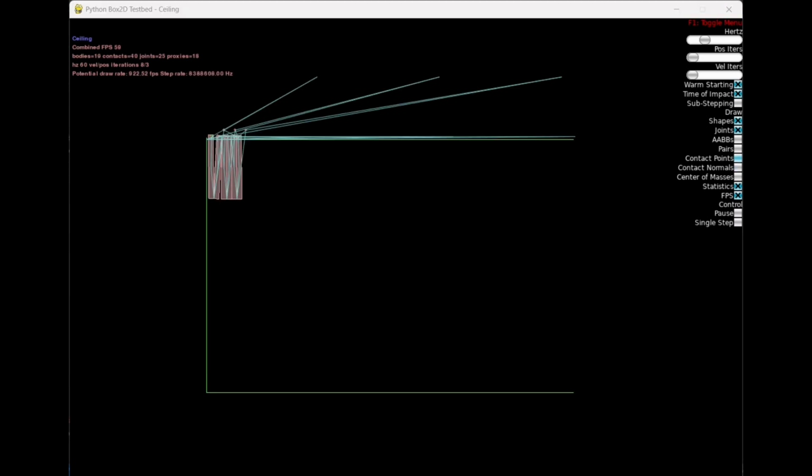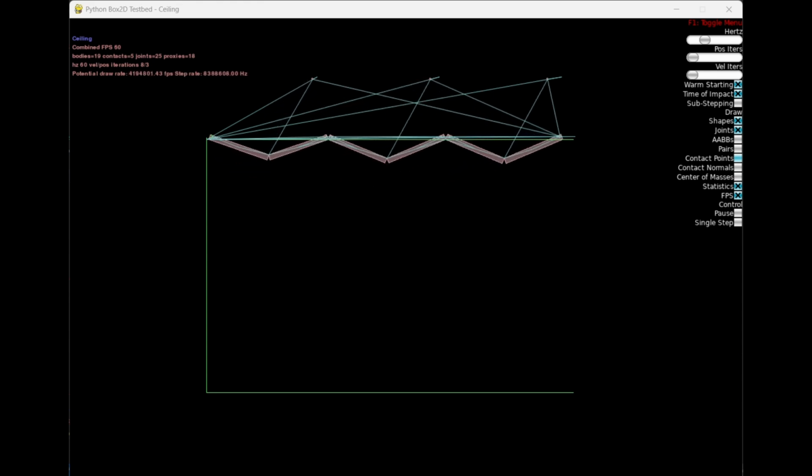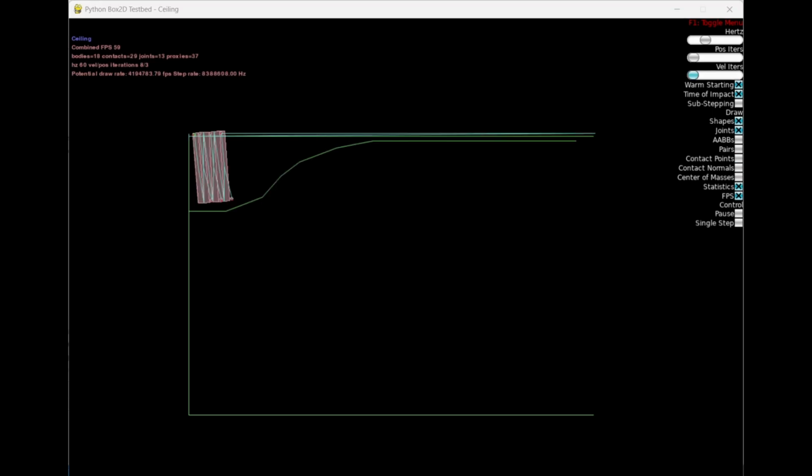I gave some thought to putting in a cabling system, which somehow pulls the panels upward by the same force that's pulling them outward. But that's pretty complicated, and even that couldn't quite get it flat. That final bit of motion, just to close the panels, is just too much force. So I thought of a different way to apply a force, adding a second rail and a set of wheels on the lower section of the panels.